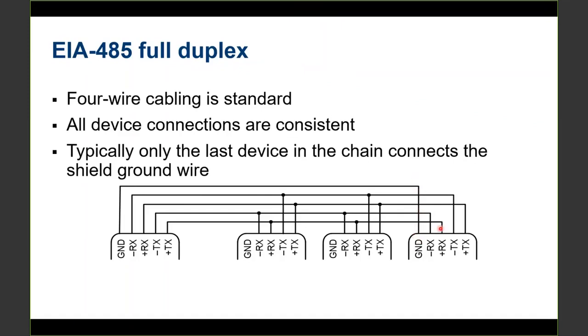So basically, that's protecting these 4 wires. Basically, it's also shielding it from more noise. But when you're measuring now, instead of measuring to ground, when we're transmitting, we measure from the TX plus pin to the TX minus pin, and that's how you get your signal. Same with the receive. You would measure the receive plus and the receive minus, and the difference between those voltages. That's how you recreate your signal,